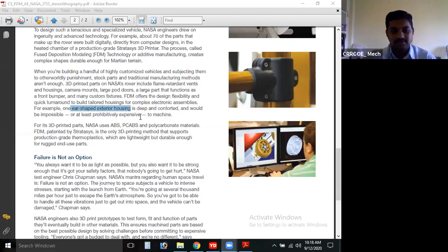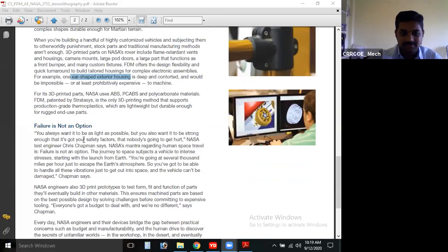When coming to additive manufacturing or 3D printing, if you want to provide the same grooves or holes, we have to develop the outer surfaces. That means other than the hole, we need to develop the other area of the component. So layer by layer it takes much time. Preferably for that application, they will go for CNC machines. So additive manufacturing is not always suitable, and traditional manufacturing is not always good.